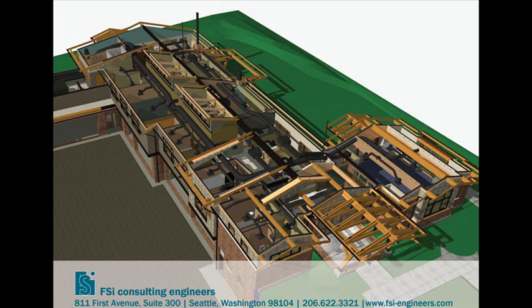So just real quick, the GSA building, how big is that building? It's about 100,000 square feet. And how long did it take you to do? I traced the background in about 4 hours, and then we did field work over 2 days. The first day was to map all of our proposed routing, about 4 hours in the field cleaning up our proposed routing, and then another 4 hours verifying existing connections. So about 12 hours to do a 100,000 square foot building. It's fairly quick once you learn how to use it and realize that you do not need to model every last doorknob, and you can still get what you need.